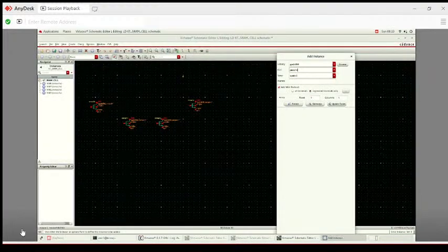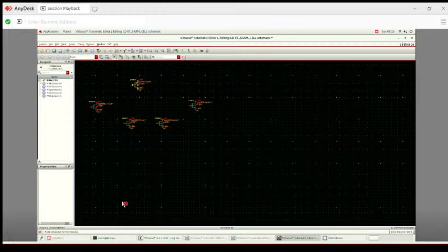Okay, so here I have placed transistors, 2 PMOS and 4 NMOS transistors. Here the 2 PMOS transistors will work as pull-up MOSFETs, and of the rest 4 NMOS, 2 will act as access transistors and 2 will act as pull-down transistors. So we have placed all 6 transistors which we required. Let's move forward.